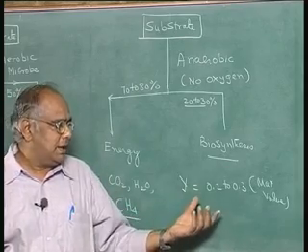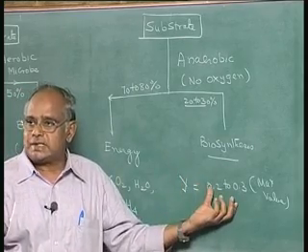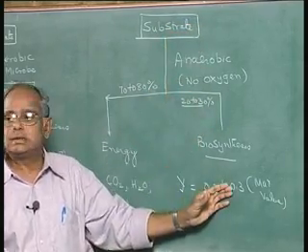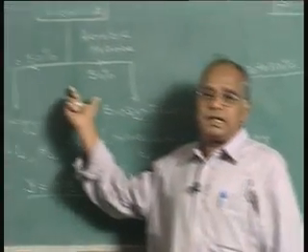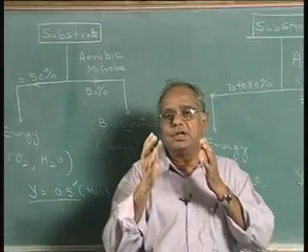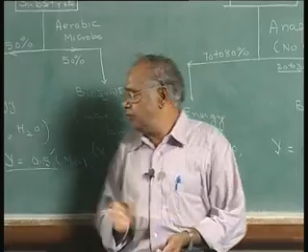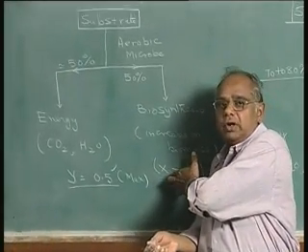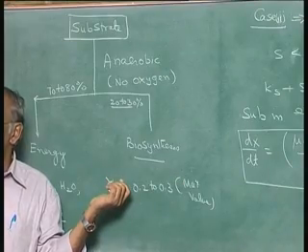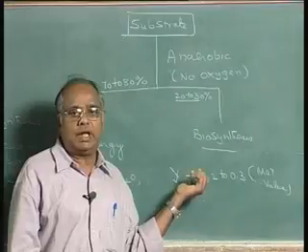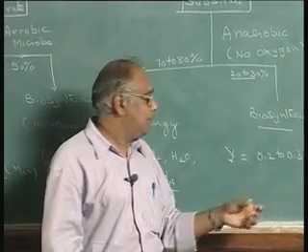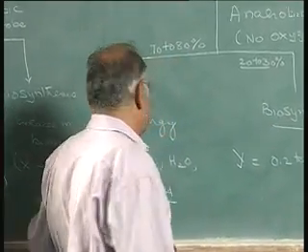So the yield of microorganisms in an anaerobic system for the same amount of substrate is less, and for an aerobic system it is more. That means if you employ aerobic systems for wastewater treatment, you will produce more microorganisms, and you will produce fewer microorganisms in anaerobic systems. This is one of the differences we can right away say between aerobic and anaerobic systems.